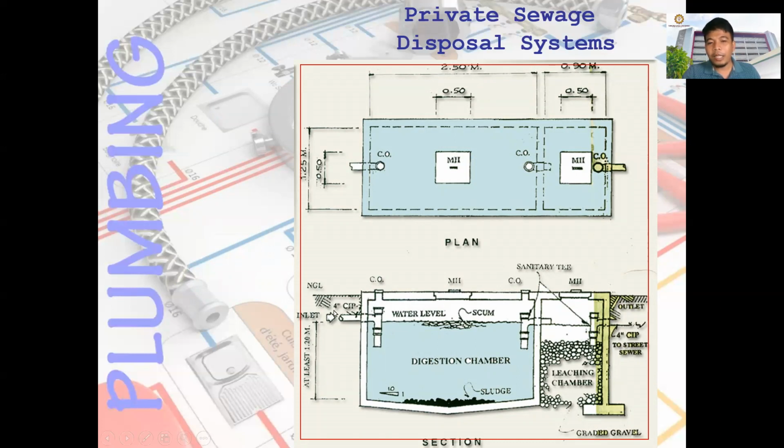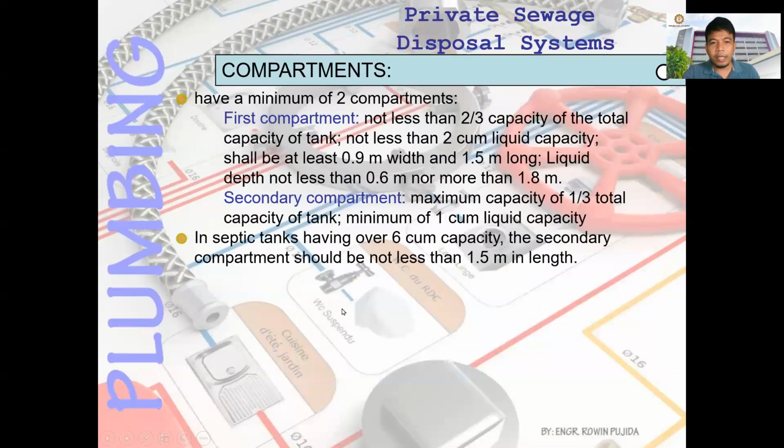So normally you have 4 inches for the air level. You have the air compartment for this, since you need also an air so that the flow of liquid here in septic tank can directly flow into pipes. Okay, so you have 4 inches, so based on design.